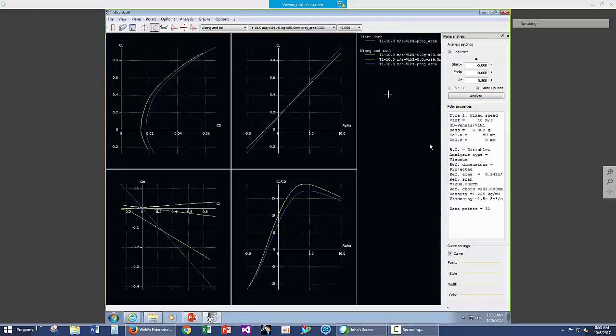Okay, so now for CG is 80, we've got the yellow curve. It's shallower than the blue curve. That's looking good, but it's too low. We want to raise it up. And to raise it up, this is how you trim your airplane with your elevator. You can have a series of lines that are all parallel to the yellow line for different angles of attack of your elevator, or different elevator setting angles.